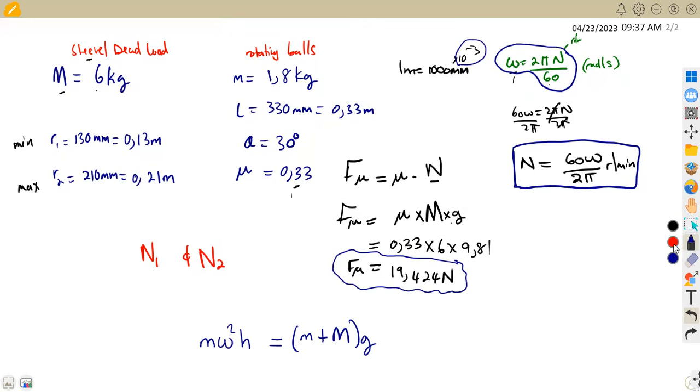Here we have a frictional force in this question. There is a frictional force that is operating. So on this weight component, where there is a combination of the balls and the sleeve, we are going to subtract the frictional force that is on the sleeve. This is the difference from the normal formula that we had before.